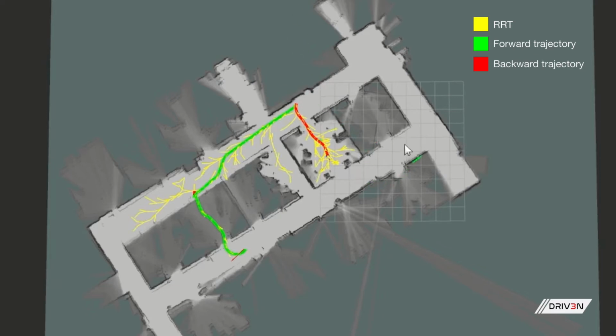After generating a successful trajectory, the path was modified using Dubin's curves. In order to implement a more accurate trajectory tracking algorithm, the final trajectory stored pose and steering angle information with each point, in addition to absolute coordinates.